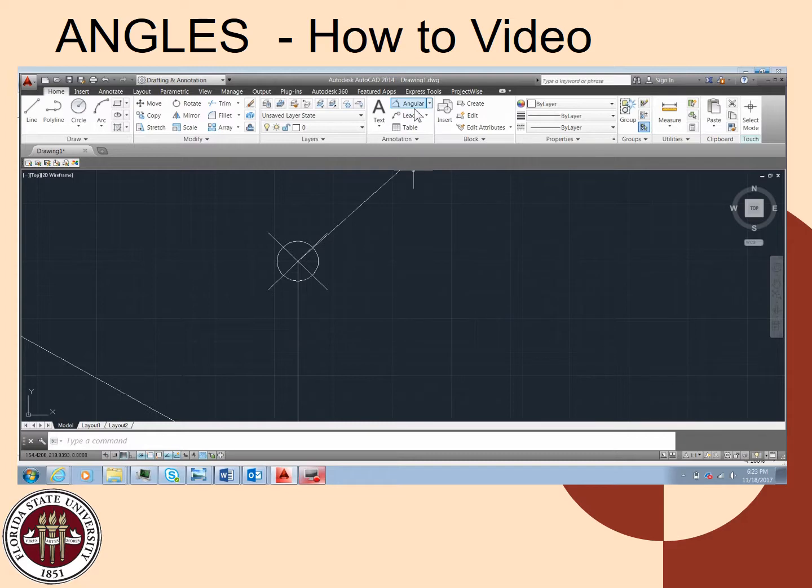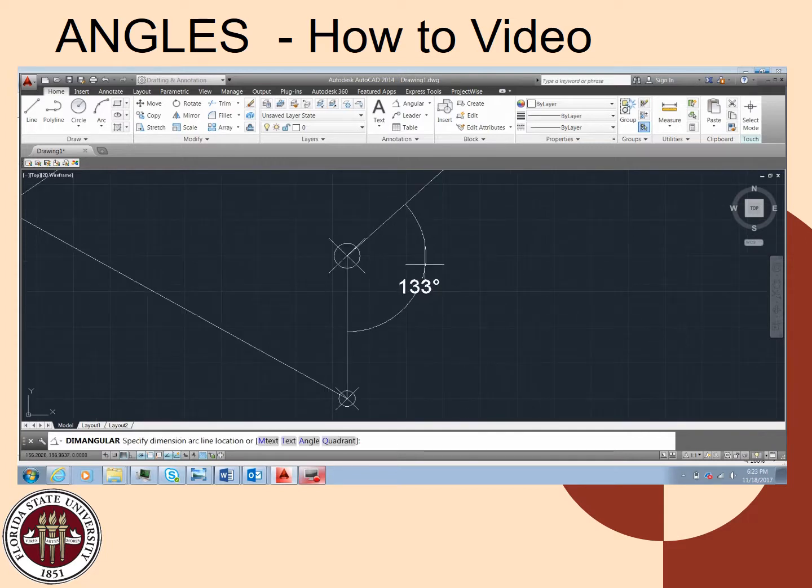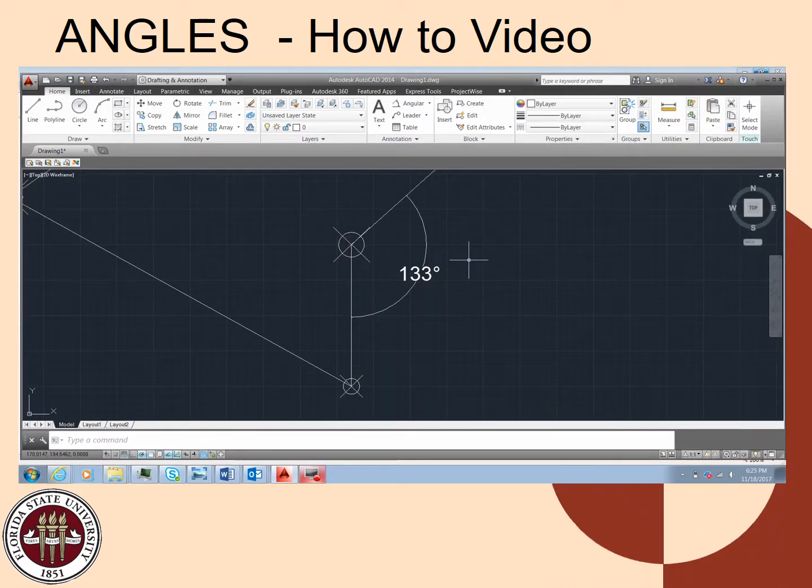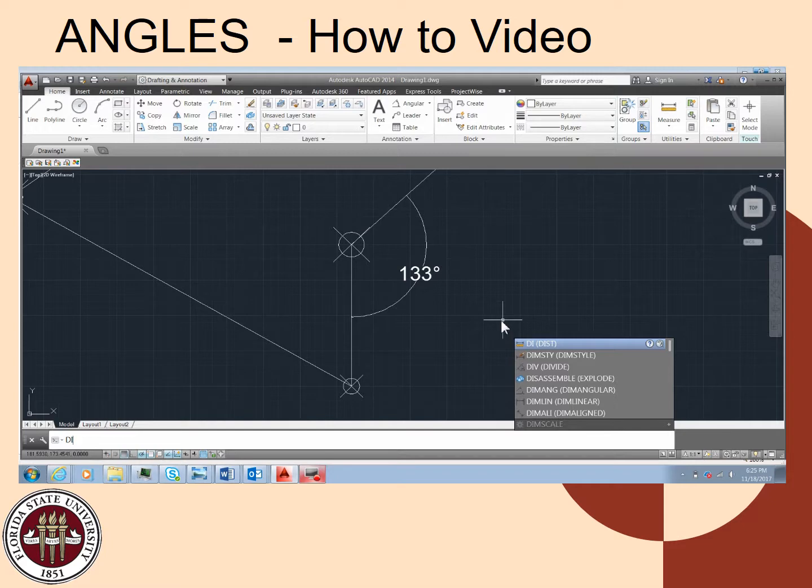In order to make an angle dimension, I can use the ribbon, or I can type dim angle. In this case, you just select each one of the items you're going to measure between, and it gives you an angle. Notice it's only 133 degrees. The precision is not set correctly, and I need to fix that. 133 degrees does not give us much precision at all.